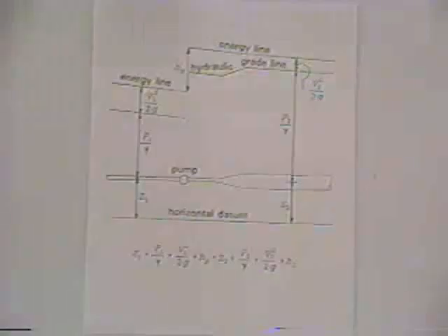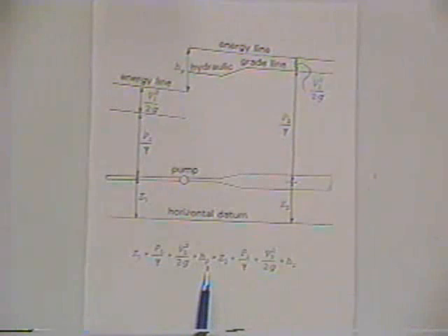So that's just to think intuitively as far as pressures and heads in a pressure conduit system. And many of the problems that you solve are just a trade-off, as we said already, between the different forms of energy: the elevation head, the pressure head, the velocity head. And this illustrates some of the trade-offs, and it also illustrates that we can actually add energy to the fluid in the form of a pump. Head losses remove the energy, but we can also add energy in the form of a pump.